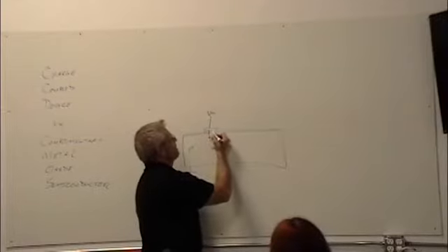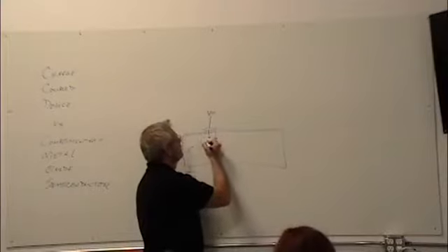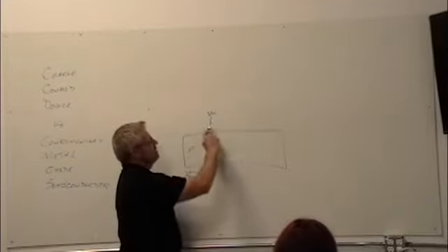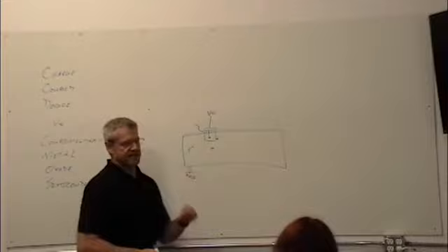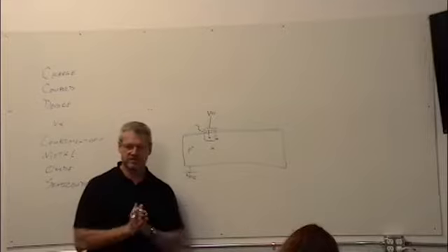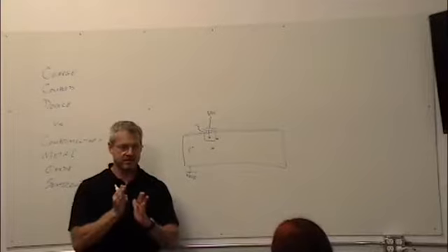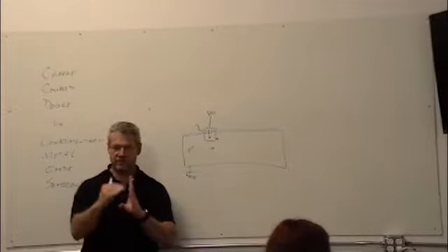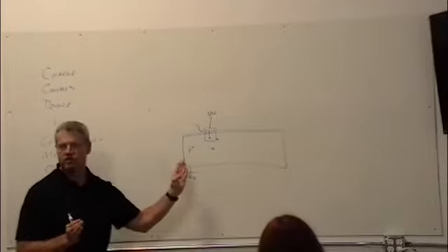This creates a very intense electrostatic field in here, and it creates here what we call a potential well. This gap here is angstroms. Remember we talked about a million years ago, the capacitance of a capacitor is the plate size and the distance across them, so the narrower that gap becomes, the more capacitance you get for a given unit area, and that's because of field strength in there. And the field strength gets huge in here.